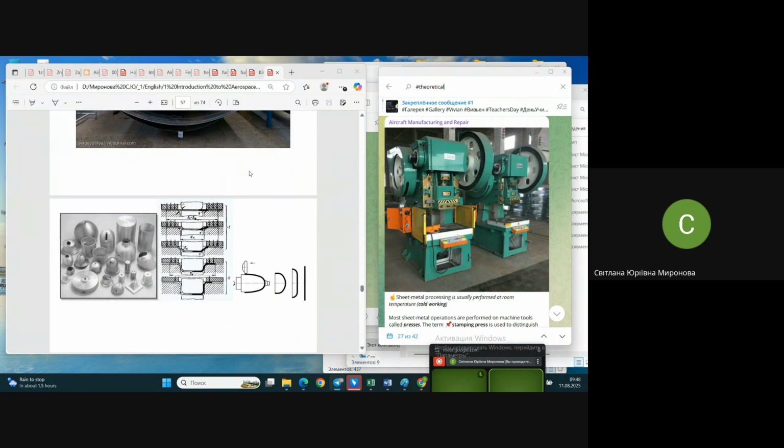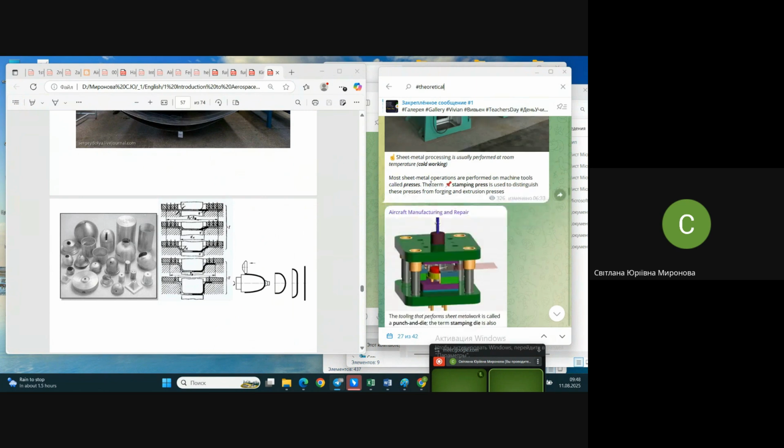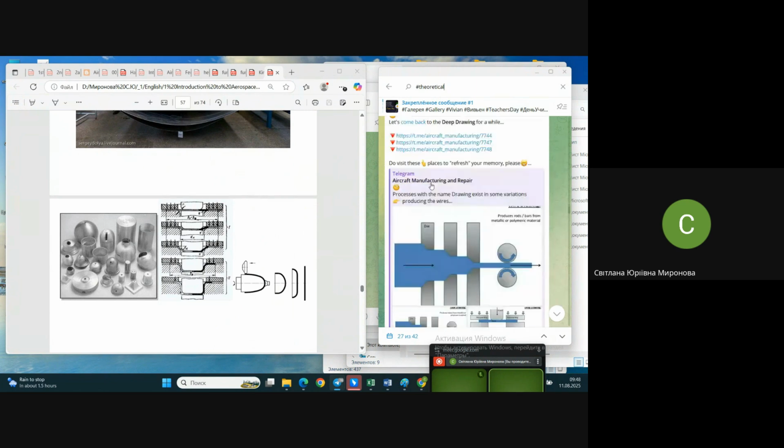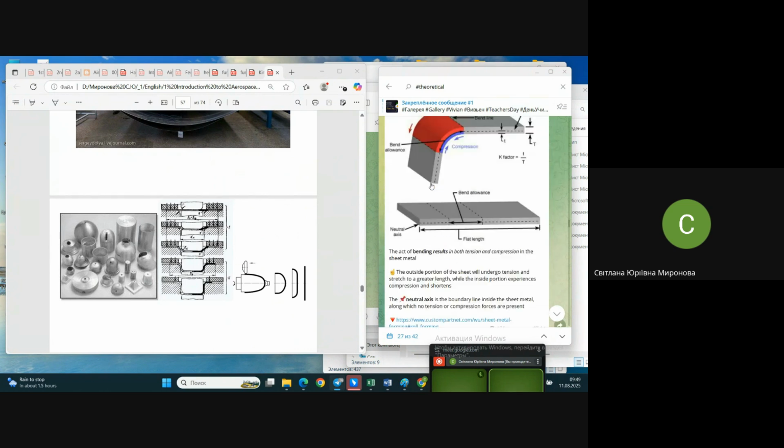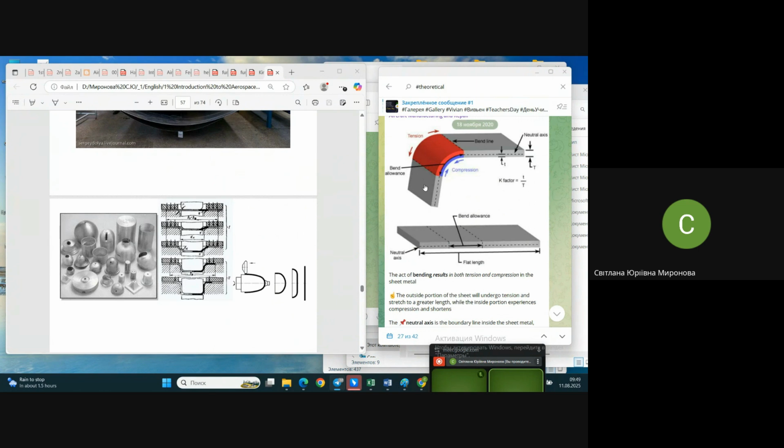Very well. Where we stopped yesterday: what is the problem during sheet metal stamping in case of bending, especially in case of some techniques of flanging and forming? I hope you do remember, it is the spring back effect, when the material spoils the shape after it was bent or after it was deformed. And besides this struggle with the spring back effect, another direction of our work is